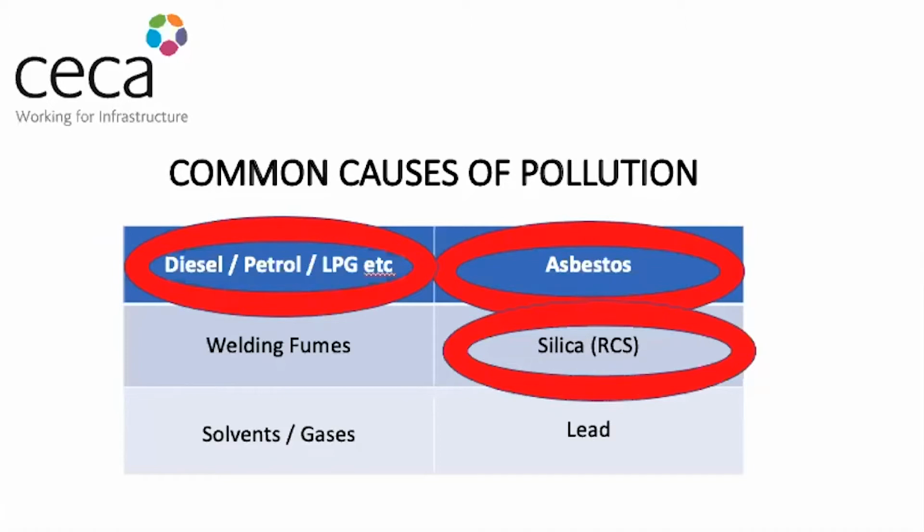And breathing diesel fumes can cause a number of ill health effects. Short-term exposure is probably not too bad. It may cause eye or respiratory irritation, and you can get rid of that just by going out into some fresh air. However, longer periods of exposure, in particular to any black or blue smoke, can lead to coughing, chestiness, and even breathlessness. You might think that's not too bad either. But there is evidence, and the HSE have done quite a bit of research on this, that repeated exposure to diesel fumes over many years can increase the risk of lung cancer.